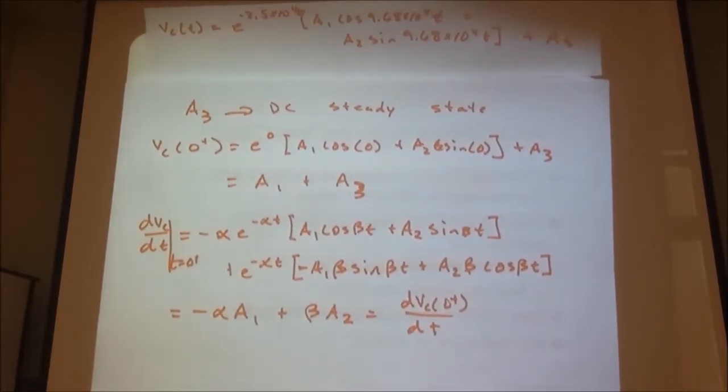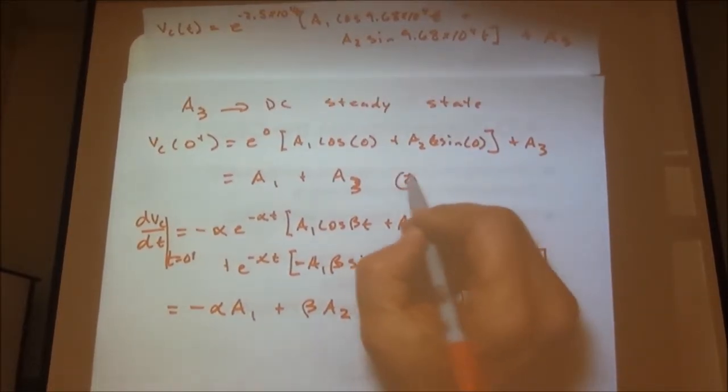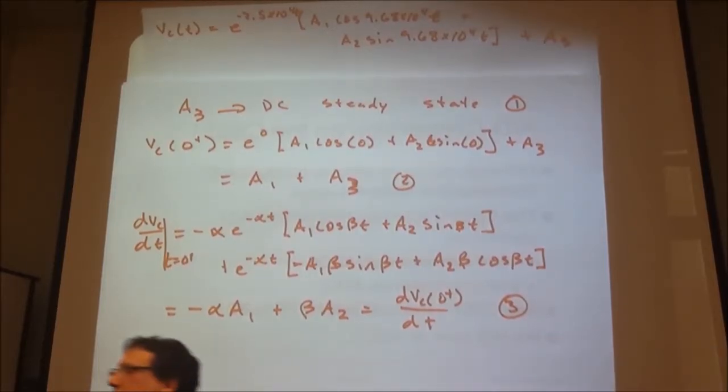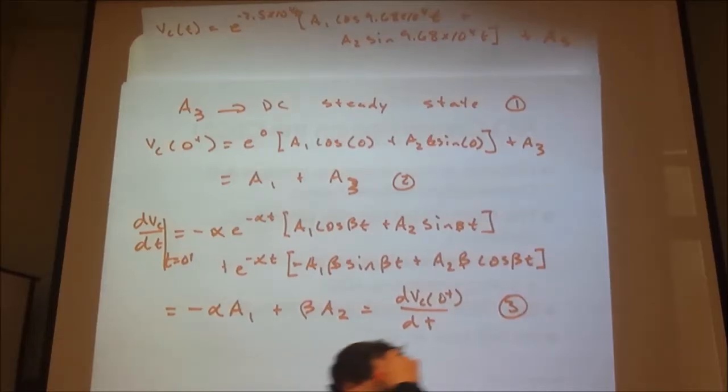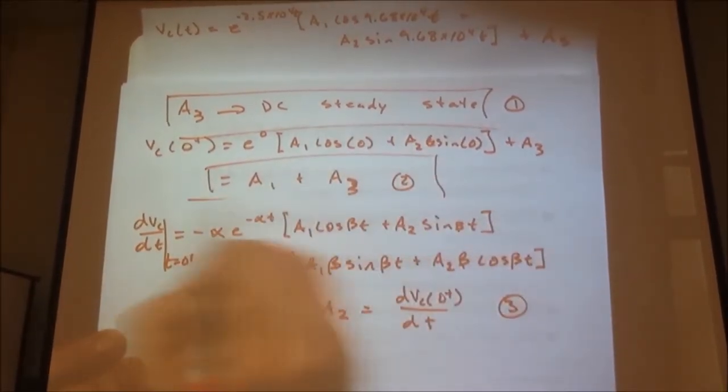So here's our general expression. Once you know what alpha and beta are, you can find all our coefficients, of course. A3 from the steady state. And again, it becomes a fairly mechanical problem. This generally applies. So, once we have an underdamped case, you can write these down. These are boxable, in some sense. Once it's underdamped, this is true. And the same was on the other ones, even though I didn't write it.